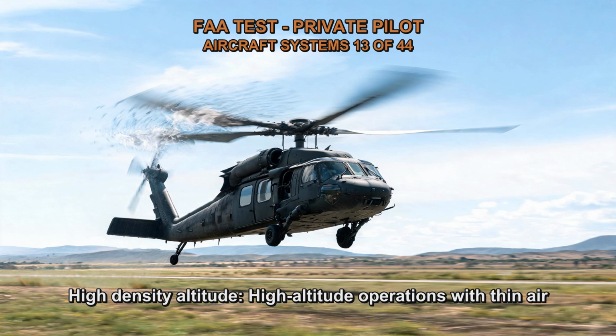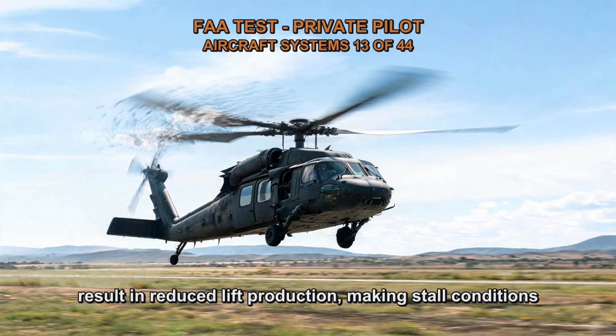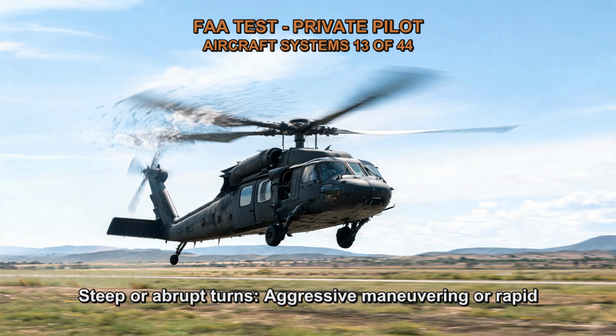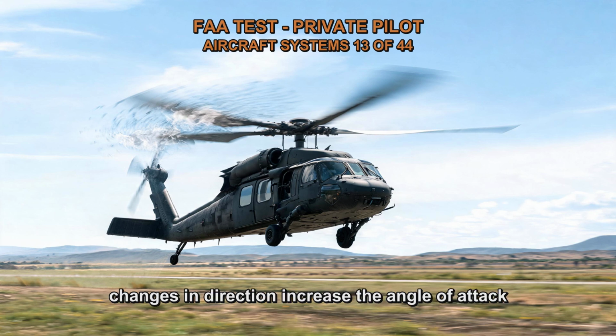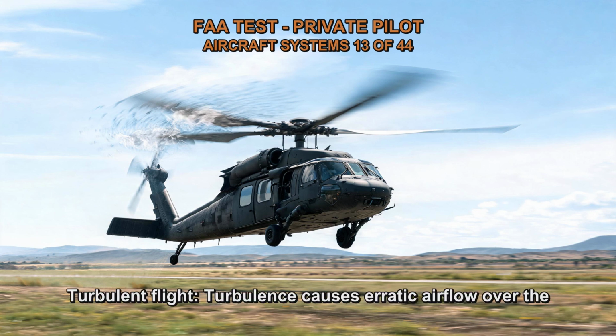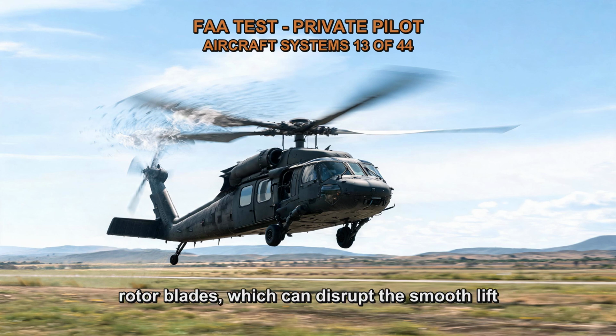High-altitude operations with thin air result in reduced lift production, making stall conditions more likely. 4. Steep or abrupt turns. Aggressive maneuvering or rapid changes in direction increase the angle of attack on the retreating blade, elevating the risk of stall. 5. Turbulent flight. Turbulence causes erratic airflow over the rotor blades, which can disrupt the smooth lift production and lead to stall conditions.